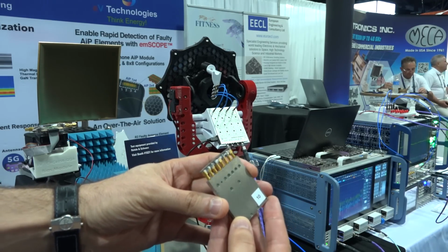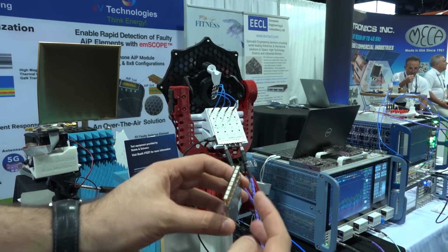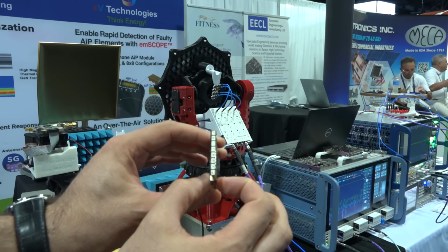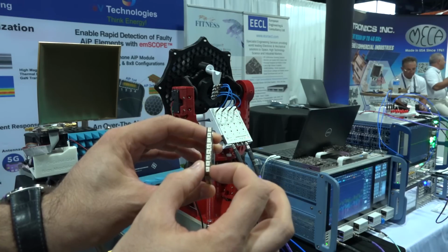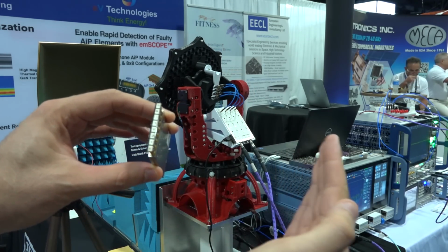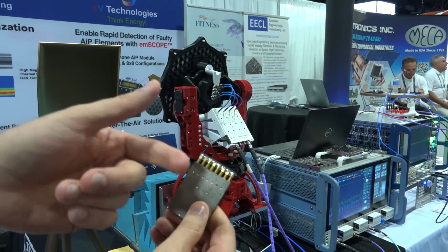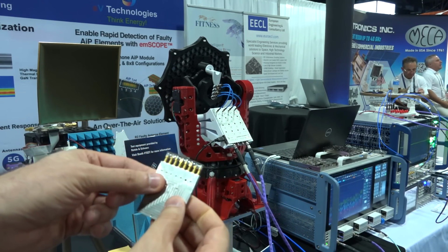This is a phased array module with all the active circuitry inside of this box and the antennas in the front operating up to 30 gigahertz. And you can see, because the thickness of this is proportionate to the size of the antennas themselves, this entire thing is 2D stackable, and you maintain your antenna spacing and your radiation pattern, and all the thermal and isolation and everything is handled in here.